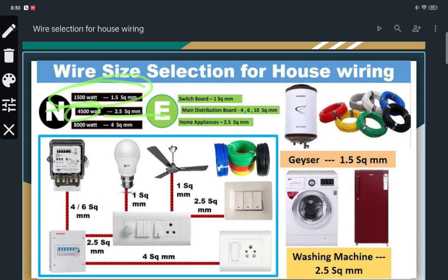Even the quality of the wire matters; we have to check the gauge, whether it is a proper 2.5 square mm or not. If you are using local quality, it may not work. You may face burning issues, and many hazards can occur. So we always recommend going with a well-known brand when purchasing wire. We also keep the wire load lower, giving a minimum of 50-60% margin in the recommended wire size.